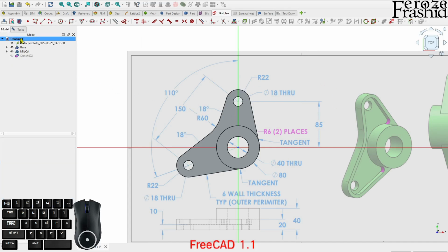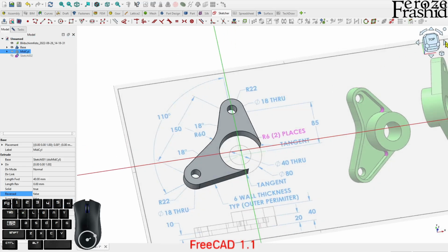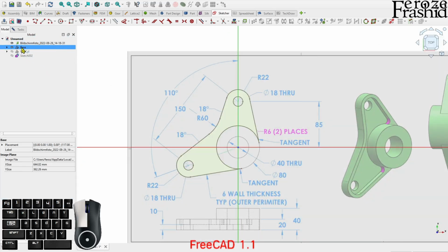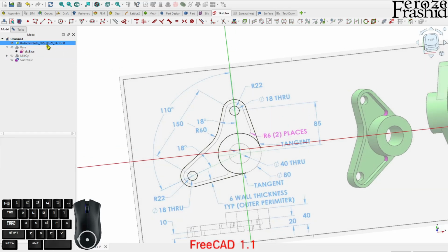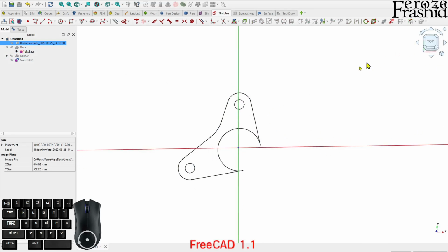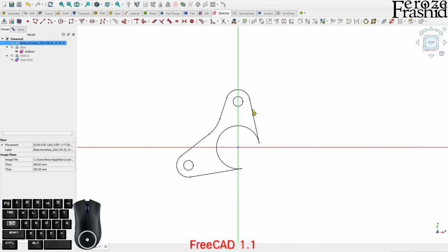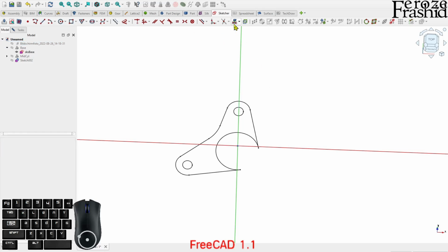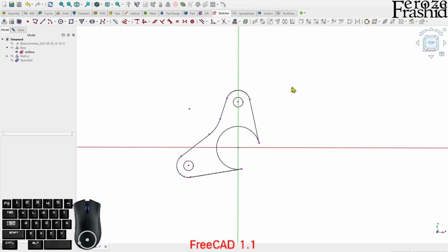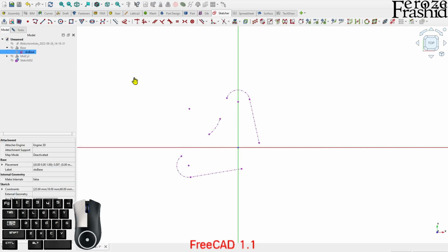Keeping that in our mind, I'm going to hide this mid cylinder, right? And then hide this base as well. Under the base, bring the sketch back. Because it is available, I want to pull in these edges from the sketch, not from the 3D feature. Because I can, because the edge is there. So let's make it construction geometry. Pull in this edge, maybe this one too. Yeah, we will just bring this in, and maybe in this one as well. But now you can hide this sketch.